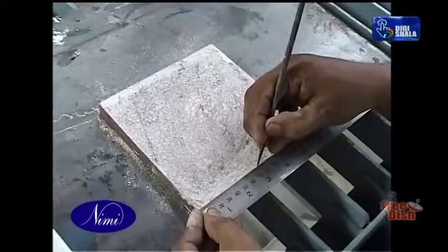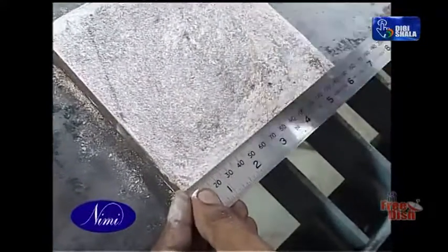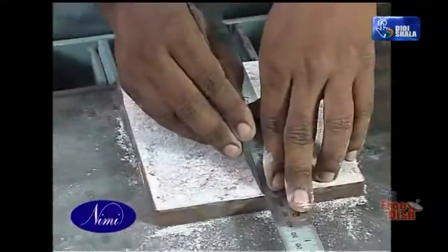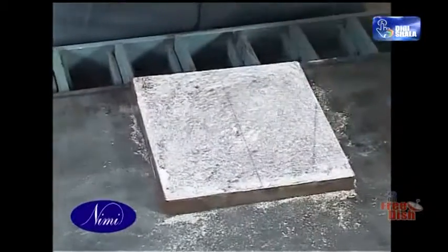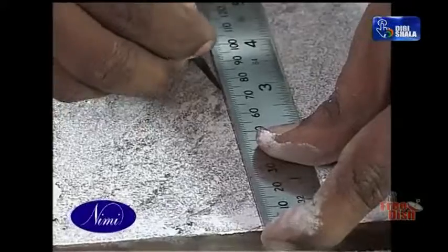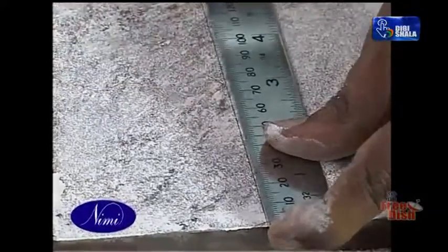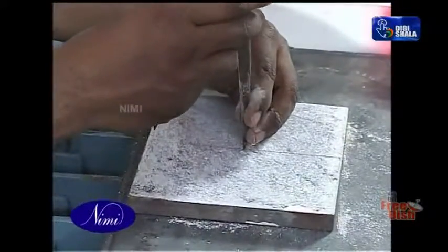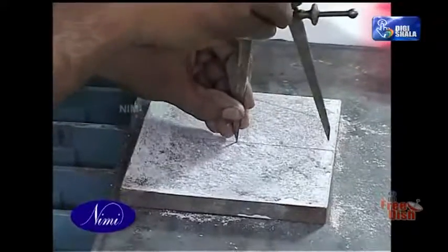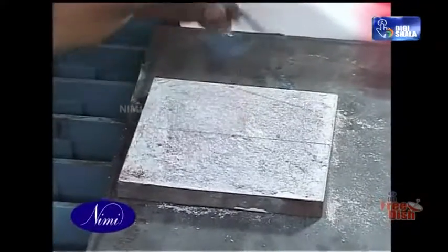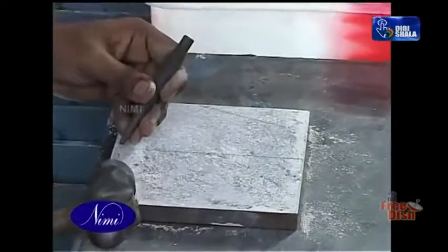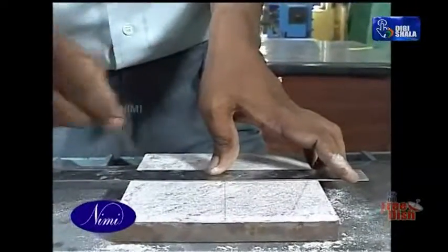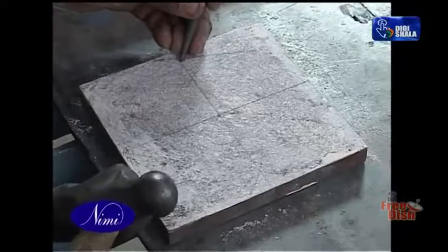Locate the axis of the plate similar to the previous exercise. Draw the center line of the axis. Bisect the center line now. Punch the center point. Take a suitable radius in the divider and mark 2 points on the two sides of the center point. Punch the 2 points. Bisect the center line, marking the second center line. Punch the reference points on the center lines.